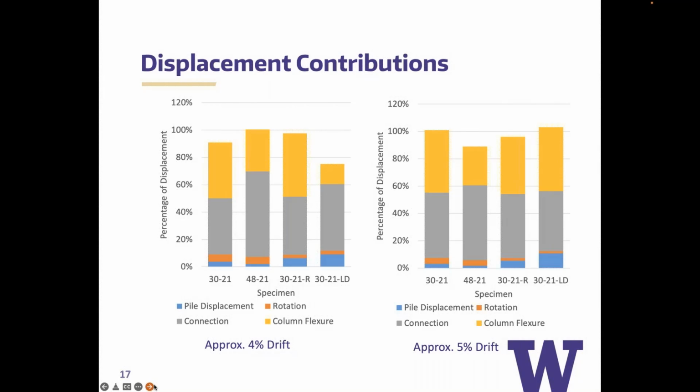Now, this may seem counterintuitive, but what's happening is the flexural response of the column, the ductility, is really through yielding of the reinforcement. And if you take that bar and you have a portion of the embedded bar having a fairly large strain, and then that strain lowers because of the bond between the reinforcing bar and the steel tube, you actually get a lot of inelastic action out of that region.